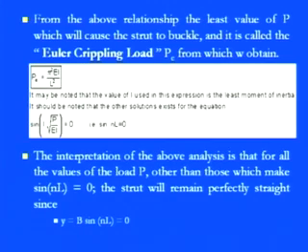And it should be noted that another solution exists in the equation, if sin NL is equal to 0. That means, keeping the square root of P by EI as n, we have sin of NL equals 0.